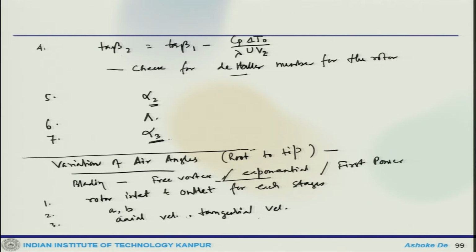Now, to calculate the dimensions upstream and downstream of the rotor, stages 1 and 2, and the dimension at station 3, we typically follow the continuity equation or the mass flow rate equation. So, for example, for the rotor, upstream is station 1, station 2, and then you have the stator, and that is station 3. Now how do we calculate?